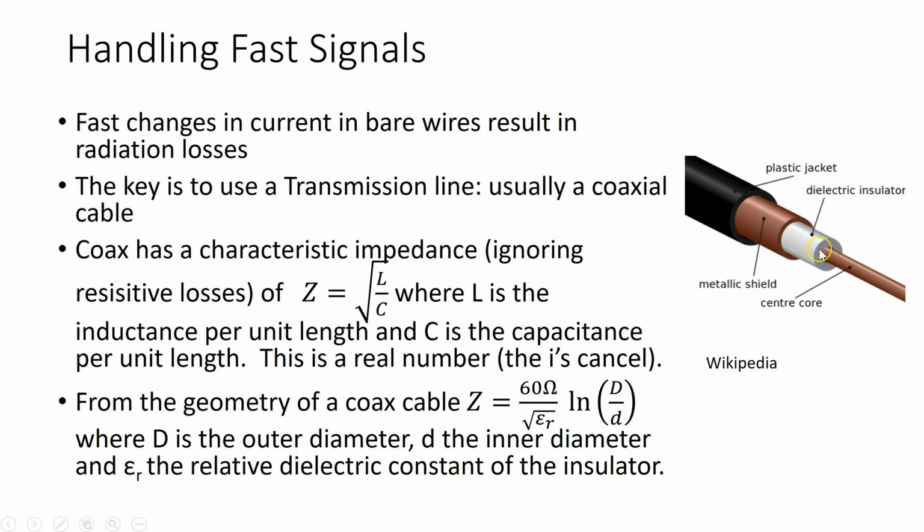They have an inner conducting core, a dielectric layer around it, an outer metallic shield, and then a plastic jacket. They're often used for very low frequencies for the very good reason that you can ground the shield and then have a Faraday cage for your low current signal, for example. Although, be warned, and we're going to come on to this topic, if you pass a very low amplitude, low current signal through this, so very small currents, the capacitance will kill you, and we'll talk about that later on.